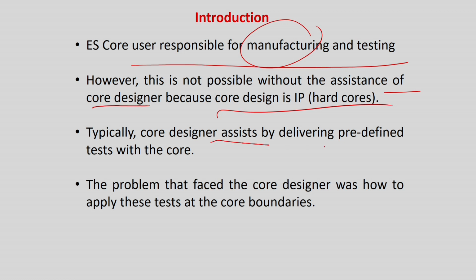So the core design assists by delivering predefined tests to the core. You will tell me that these are the patterns you apply. I assure that if you apply these test patterns, you will get 99.9% coverage, etc., for these fault models. But now the problem is, he is designing a core and he is saying that these are the pins you have to access.